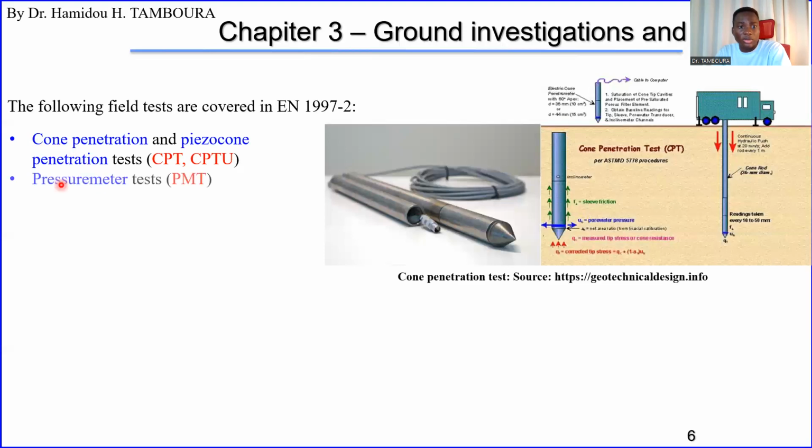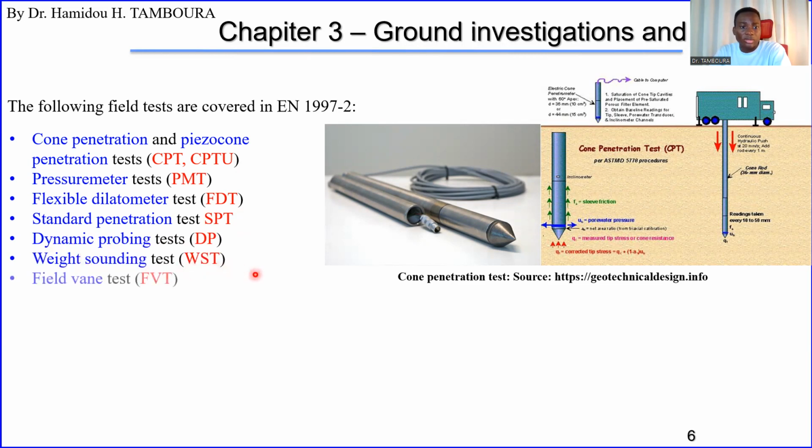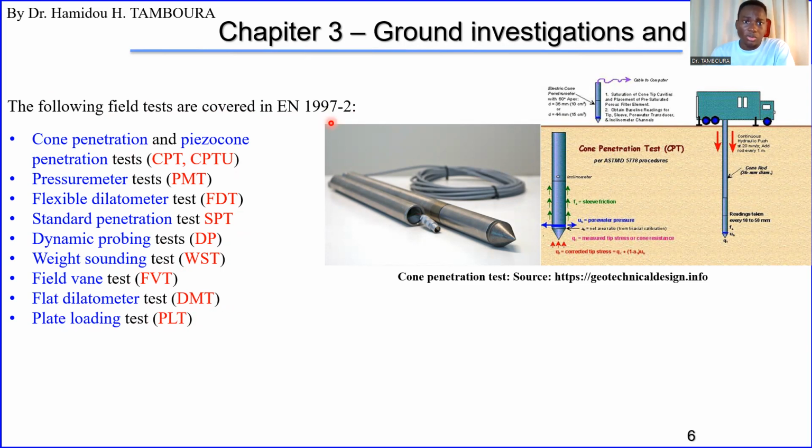So this test and also pressuremeter test, PMT, flexible dilatometer test, FDT, standard penetration test, SPT, dynamic probing test, DP, weight sounding test, WST, field vane test, FVT, and flat dilatometer test, DMT, the plate loading test, LPT, and all these tests are covered in the second part of Eurocode 7.